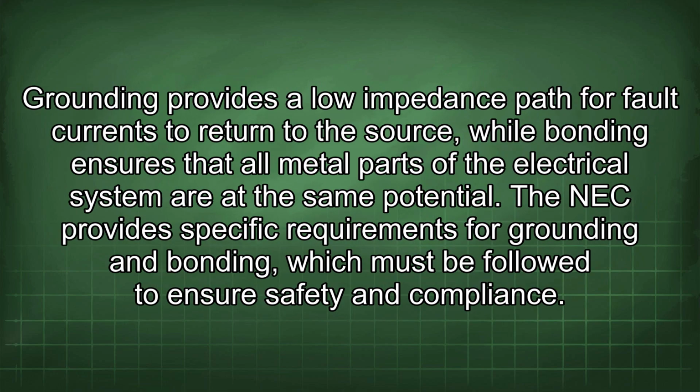Grounding provides a low impedance path for fault currents to return to the source, while bonding ensures that all metal parts of the electrical system are at the same potential. The NEC provides specific requirements for grounding and bonding, which must be followed to ensure safety and compliance.